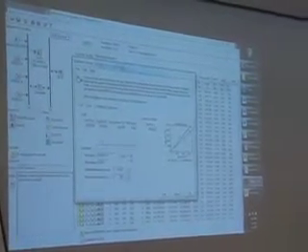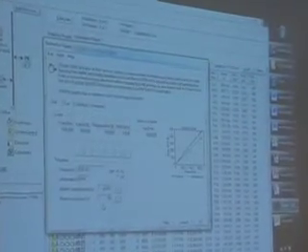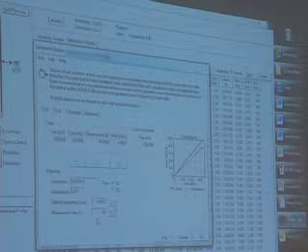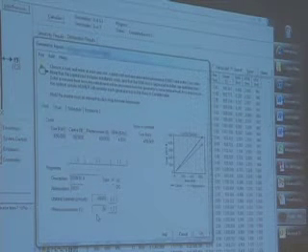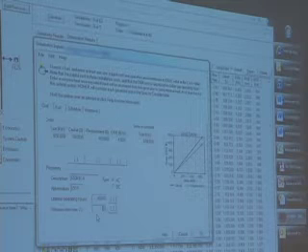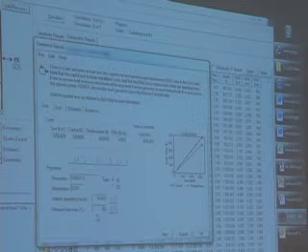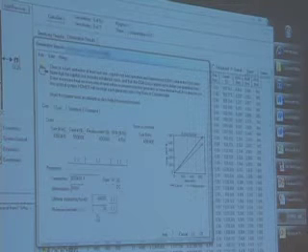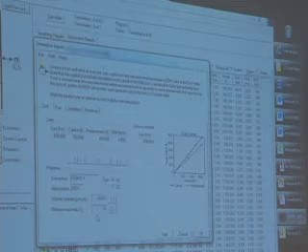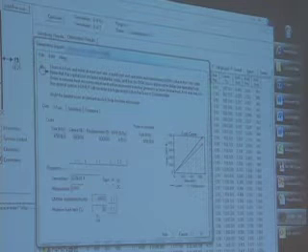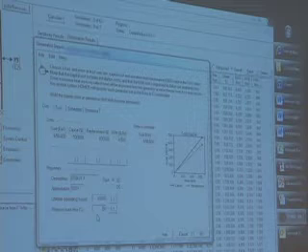So this is where you enter the minimum load on the diesel, the minimum load requirement. So if Homer decides it needs that diesel for operating reserve, but it doesn't need the power for meeting the load, it would prefer to run below 30%, in this case, of its rated capacity. But Homer will force it to run at 30% of its rated capacity. And now you have excess energy that's actually diesel energy.